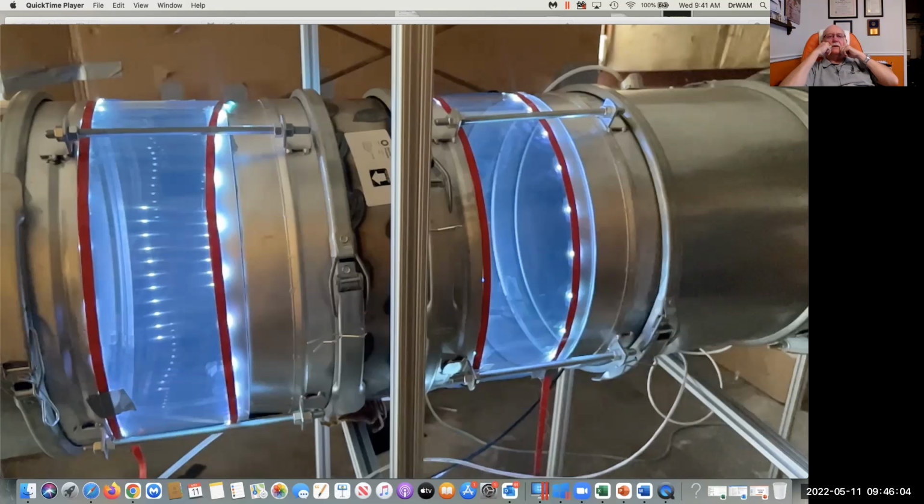Yeah, I think the one other thing with that too, on some levels I like it. I think the other issue you have is that the air handling unit is recirculating some of the air, and it's also bringing in fresh outdoor air. Depending on the outdoor air temperature, it's changing that ratio to try to minimize the use of the heating and cooling coils, staying within parameters for bringing in the correct amount of outdoor air.